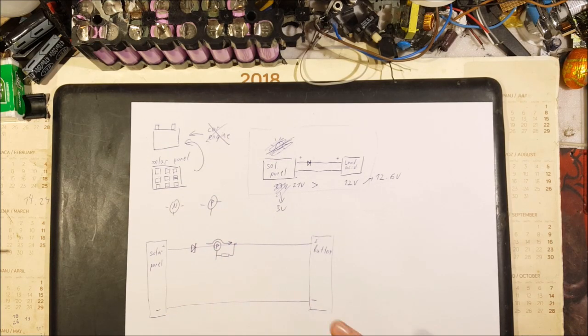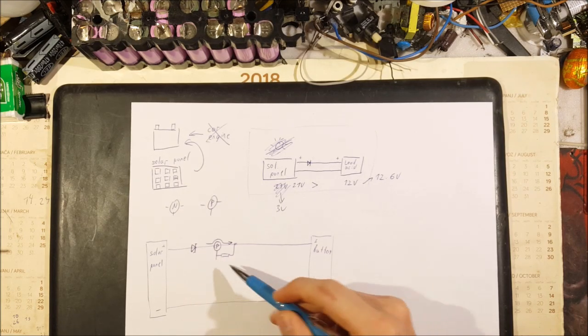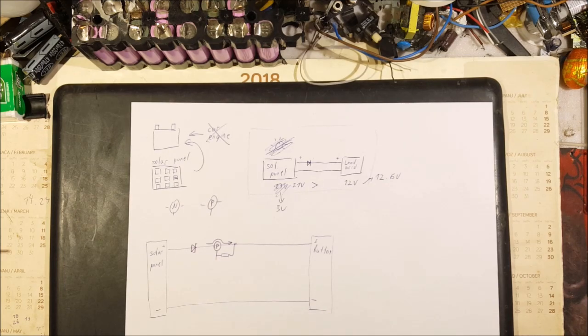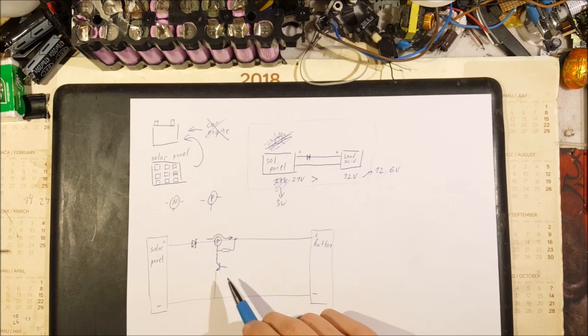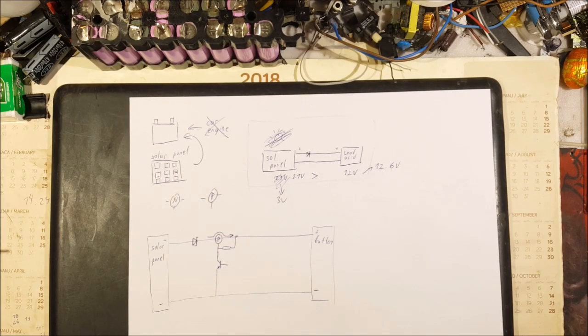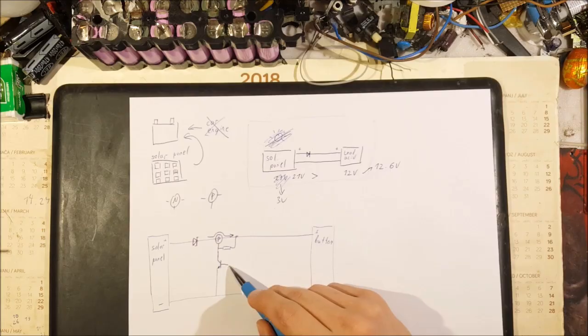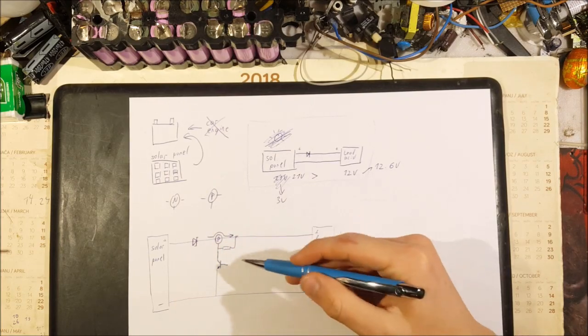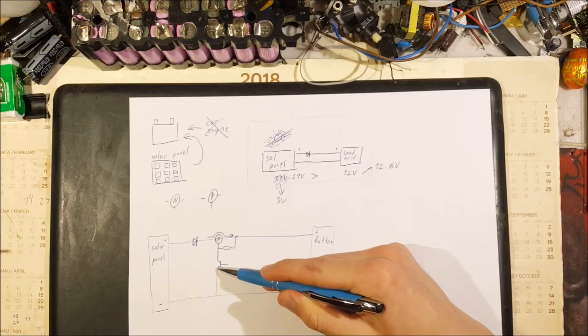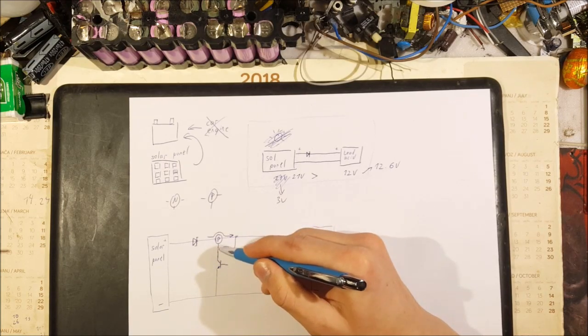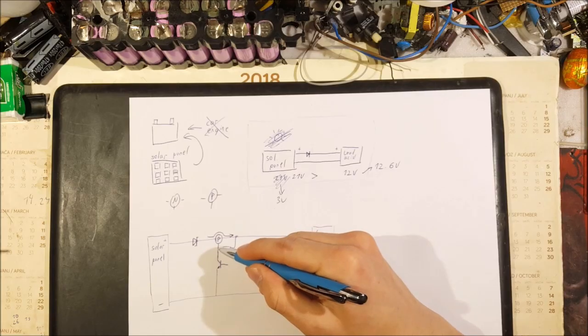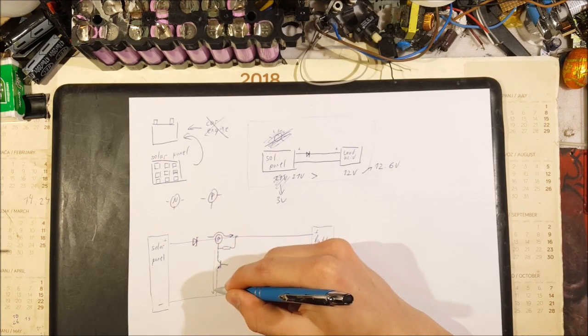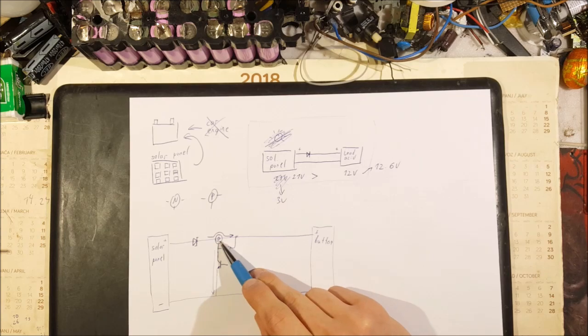Now, how do we pull this wire to the negative rail, but only when we want to? We'll use a simple NPN transistor, which, if we give it voltage to its base pin, will act like a closed circuit between this wire and this wire, thus pulling the potential on this wire down to minus and closing this P-channel MOSFET.